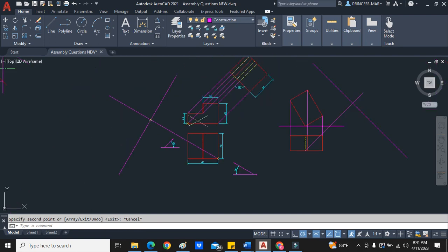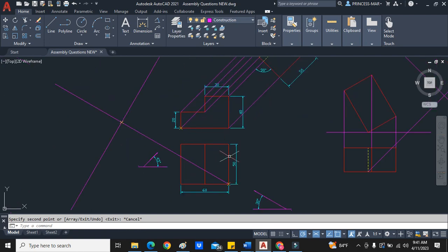Now the second step we're going to do is we're going to draw this line. But I want you to realize that when we're drawing the elevation, there's some things that you're not going to measure. So we're not going to measure any widths here. Just follow. What angle am I supposed to use? Not 45, this is the 30.